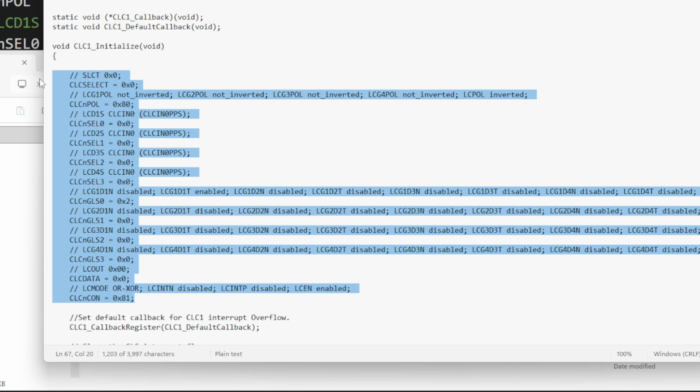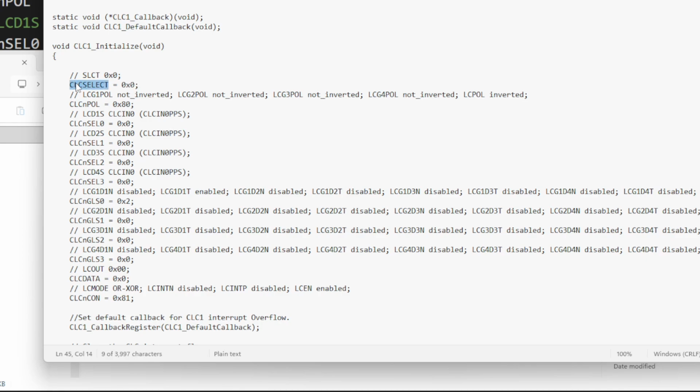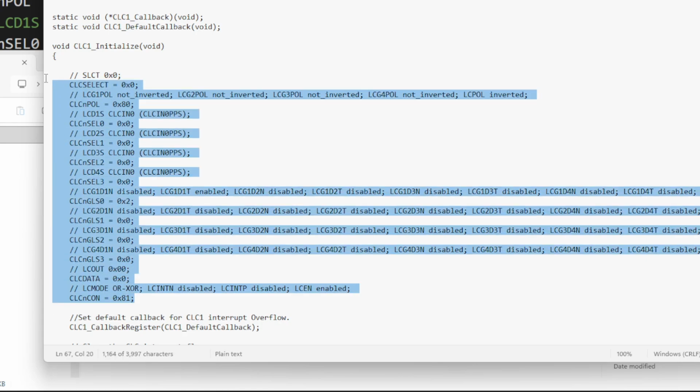So we are setting up the first CLC. So we set it to 0. We say don't invert it. And we set up a load of zeros because we didn't change the rest of the gates. And then here's our selection for the actual type of gate that we're actually running. Now, you can work through all that. Take this code, put it in GCBASIC. What else do we need?